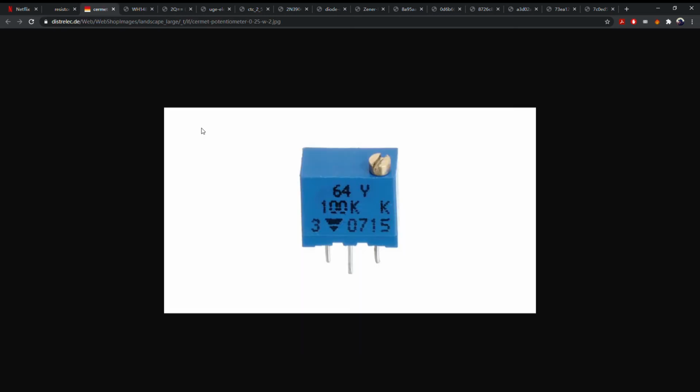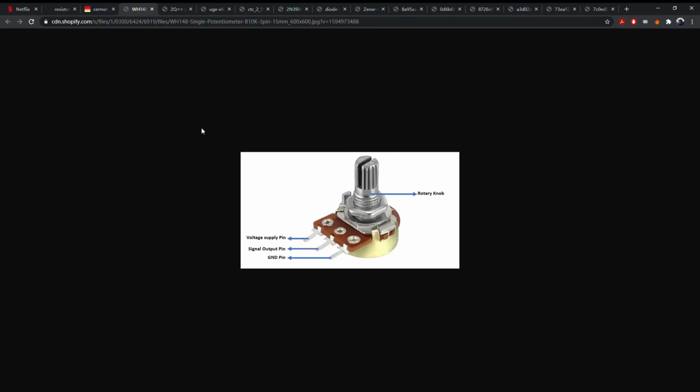And next one is potentiometer. A potentiometer is a 3-terminal resistor with a sliding or rotating contact that forms an adjustable voltage divider. If only 2 terminals are used, one end and the wiper, it acts as a variable resistor. And this one is film capacitor. In a later class we'll introduce in detail how to calculate the capacitance by the number on the capacitor.